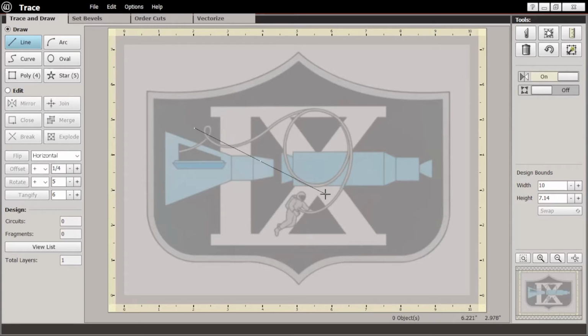If you hold down the Control key, it takes you into what's called the Orthographic Mode. And now you can only draw a horizontal or vertical line, or a 45 degree. But there's no guesswork there. And again, when you reach the end, just click, and your line is drawn, and you can hit escape if you're done with that. Okay, so that's that. That'll make things quite a bit easier for you.